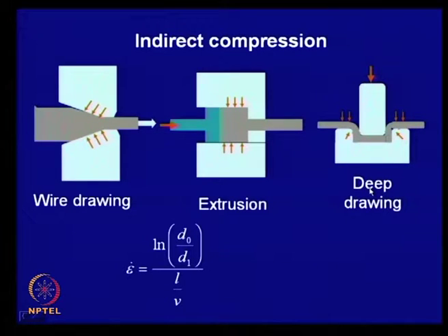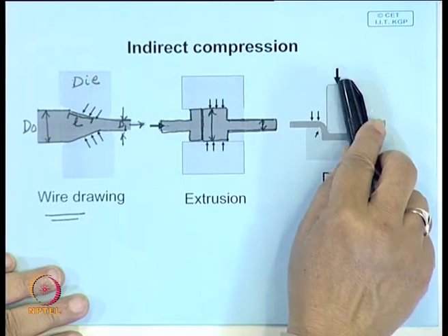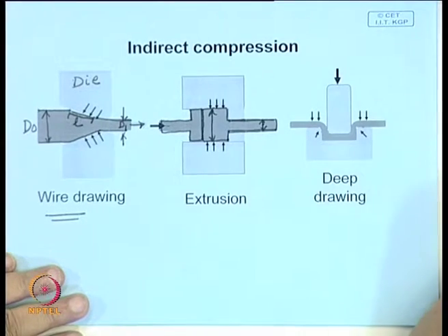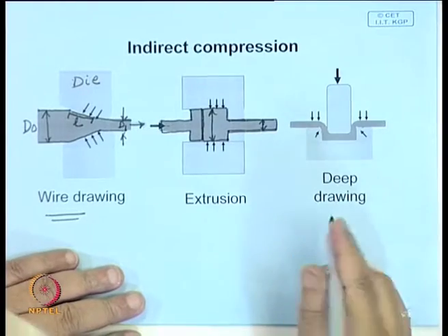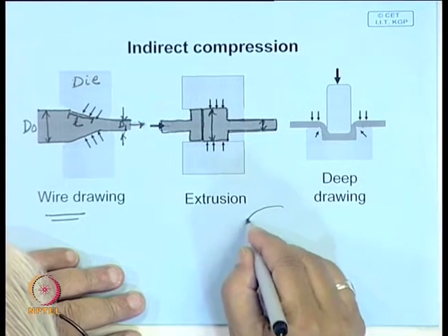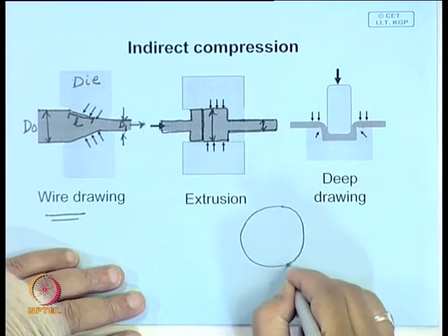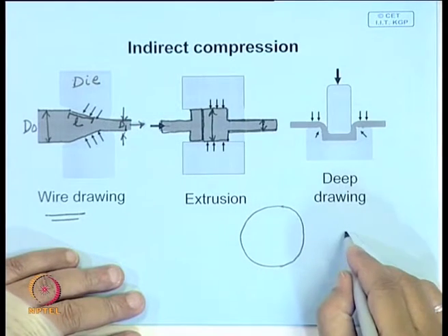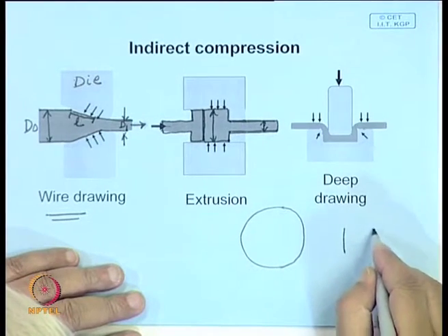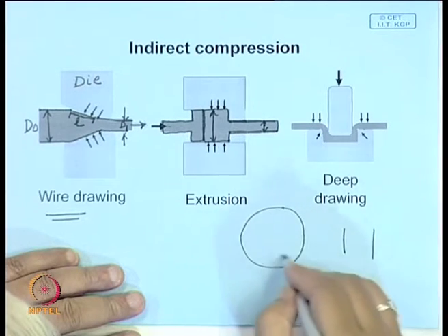Now, deep drawing is another method of forming, and we often say that this is the final step of forming. You take a thin sheet, which is placed in a die, and a mandrel pushes the material into it. Suppose you have a disc put in a die; the die is a cylinder, and this is the top view.